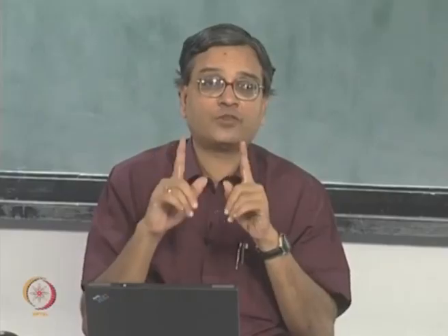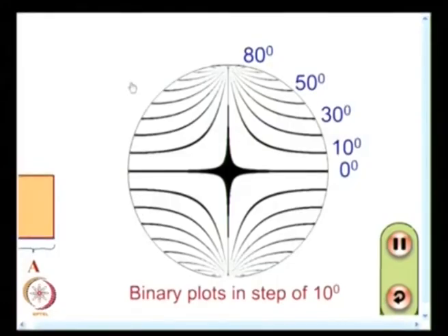And what I find here is sigma 1 minus sigma 2 contours superimposed over isoclinic contours, and I do not see all isoclinics in one shot. I have to scan the image, pick out this information, and get it as a separate image of isoclinics. So, without getting into the experimental details, I have tried to project what is in store for you. In some experimental techniques, you get the information separately.